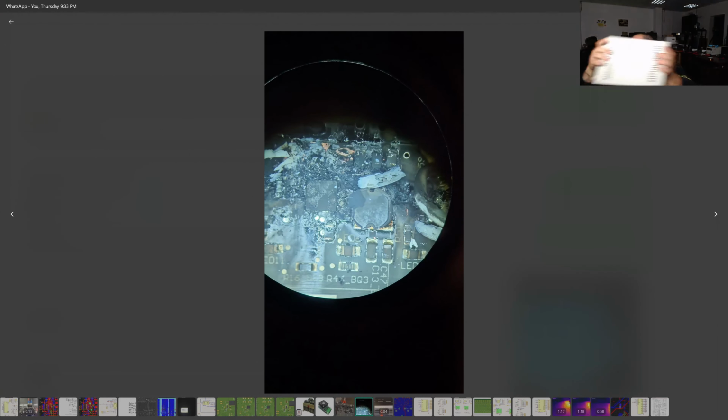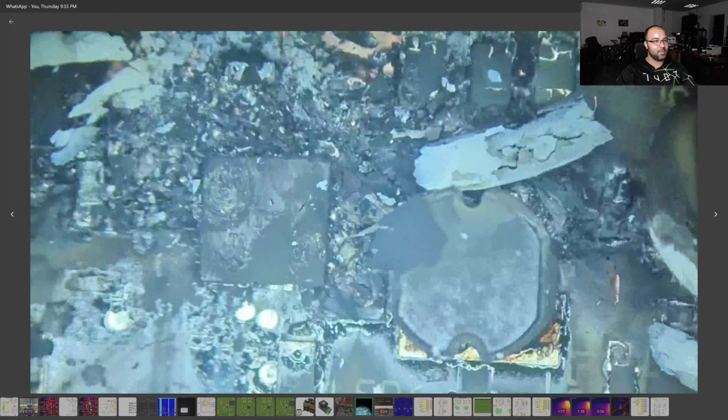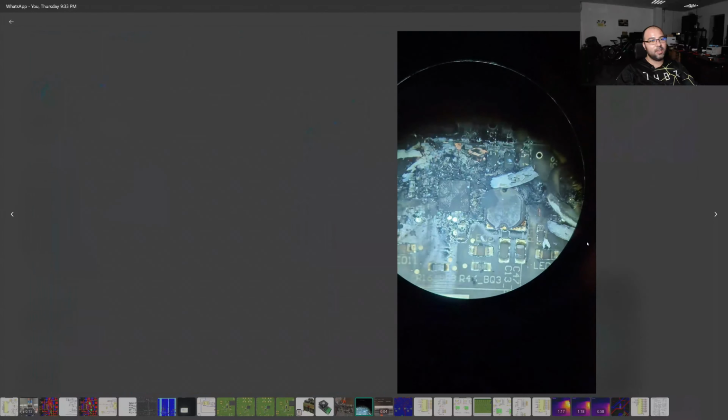So I hooked that up, and I think the ground was common with the 12 volts power supply that I used, and somehow it got energized a lot, and this happened. Like all the connected BQs, I had 4 of them connected because I was testing the communication stuff, and they got toasted instantly like fireworks.